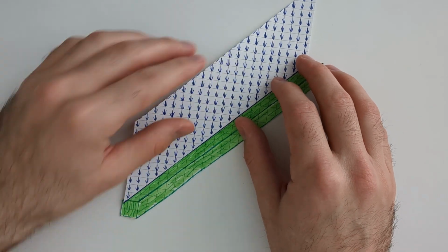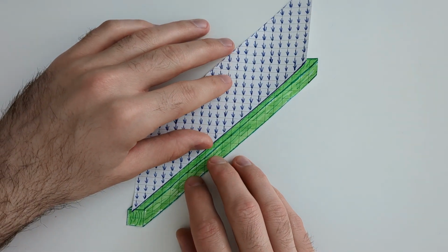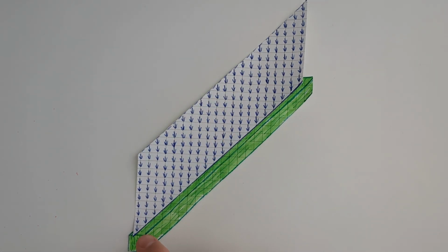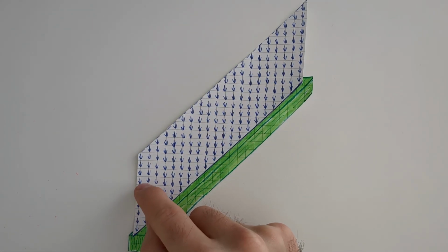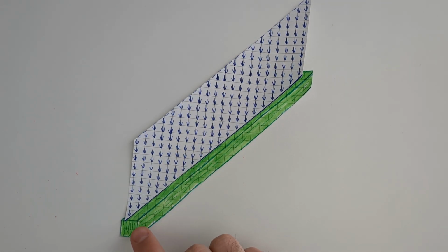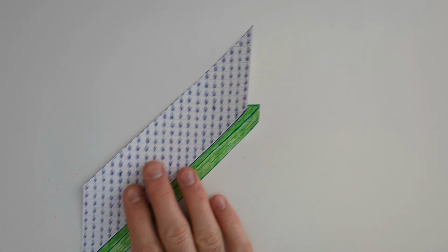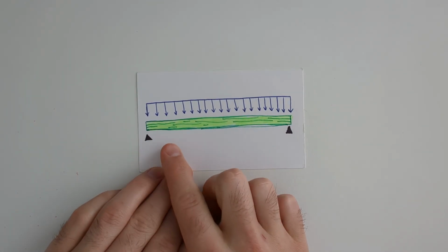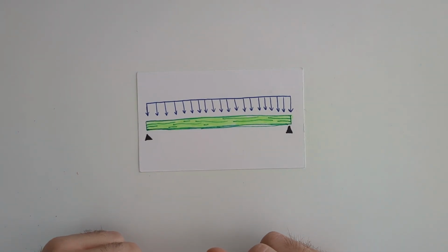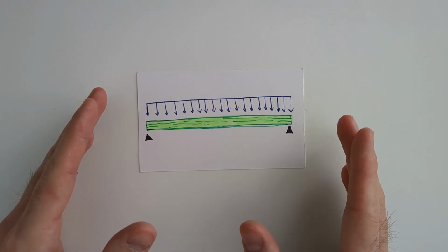Now, as I said, we compressed those arrows together into a linear load acting along the beam. And you can see here we have 1, 2, 3, 4, 5, 6, 7, 8, 9, 10 arrows acting down on the beam along each foot, or 500 pounds per linear foot. Now, all we have to do is take that linear load and apply it to our beam model. And from there, we can determine how the beam reacts and determine exactly what size our beam should be.